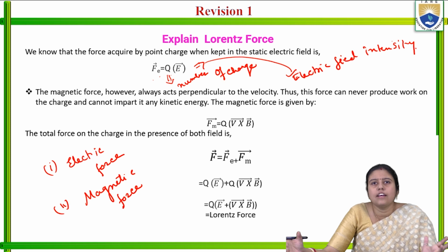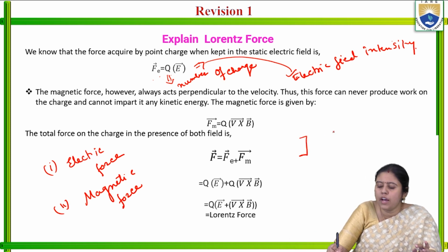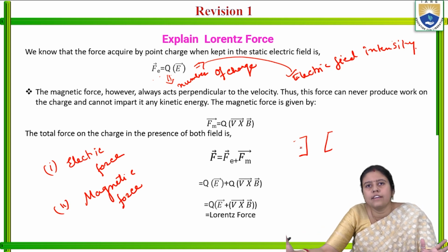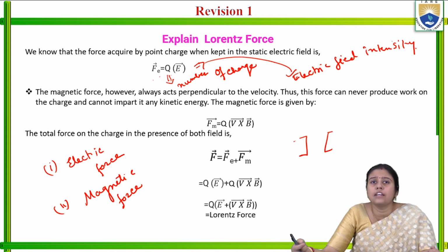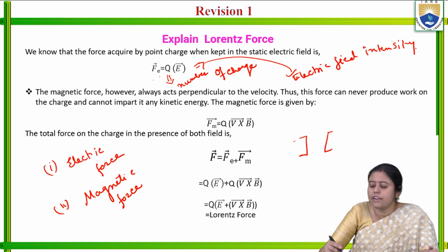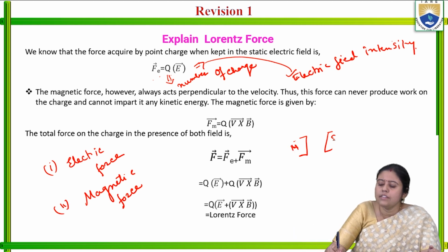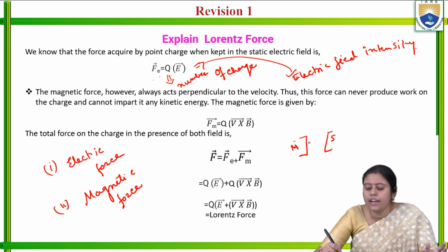Similarly, if we think about a DC machine, we give the connection to the stator and it will generate some electric field, and we get the electric force. Also in the stator, when current is flowing, it will create a north pole and south pole, as a magnetic field. Now if we keep a current carrying conductor there, it will feel some force, and the magnetic force Fm is equal to Q V cross B. V is the velocity of the charge. What is B? B is the flux density.